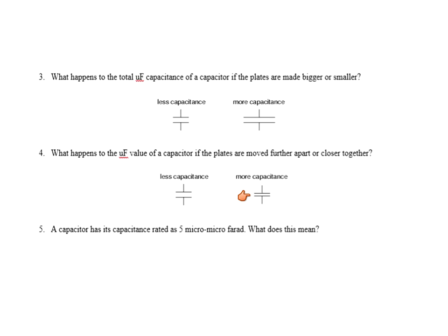So, 2 important considerations here regarding capacitors: what about the size of the plates and the capacitance? The bigger the plates, the more the capacitance. The smaller the plates, the less capacitance. And what about the distance between them? If the plates are very close together, they can attract more electrons. That would be more capacitance. If the plates are further apart, that would be less capacitance.